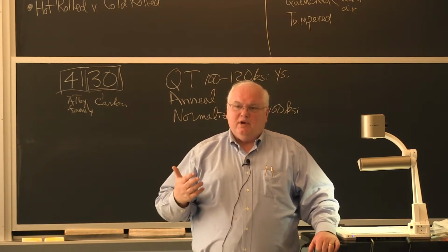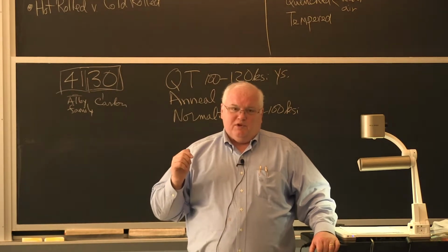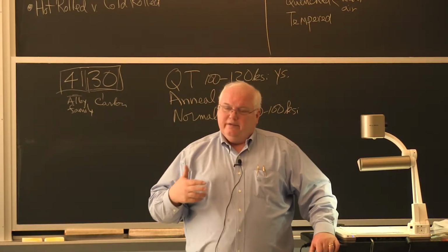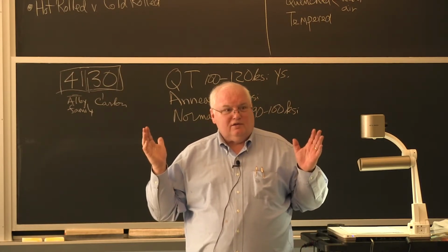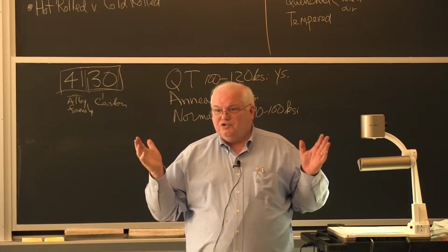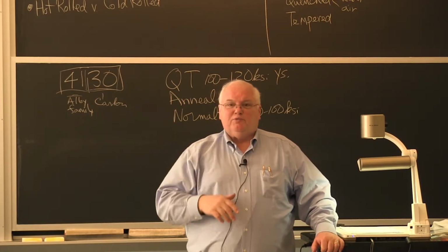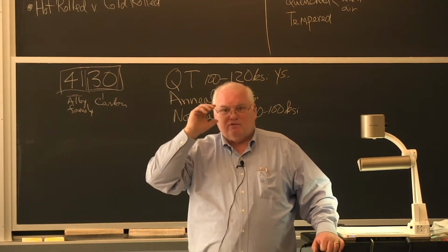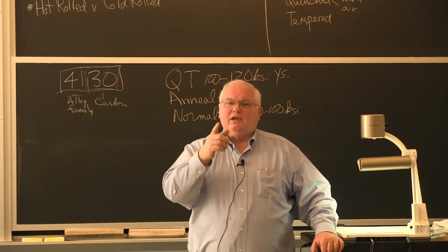So what happened here? There's nothing wrong with the steel originally from the steel mill, but there was something from the people in this little mom and pop shop in California who electroplated it. They didn't know that you had to bake out the chromium plate to get the hydrogen out. They just sent it to a plating shop, didn't tell them to bake it. The plating shop didn't say, oh, we should bake this. They should have. But they did it, sold it, and the guy's a paraplegic, yes.